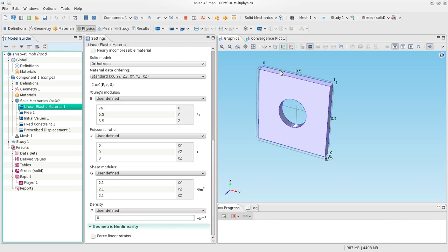So for the standard form, I only supply 9 values, and you, with the knowledge that you have, there is no way you can figure out those off-diagonal normal shear coupling parts if the orientation is not at a direction that aligns with the coordinate directions, with the directions of loading. Okay, so now therefore it turns out the material still has 9 independent components. It always does. That's the case of orthotropy. But because the orientation of the fibers are different, you have to recalculate the compliance matrix.